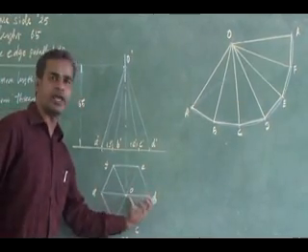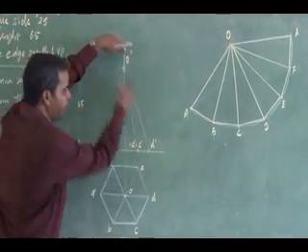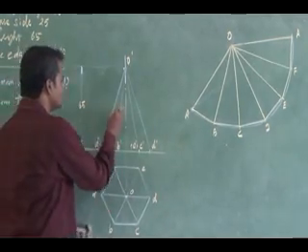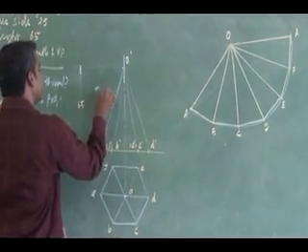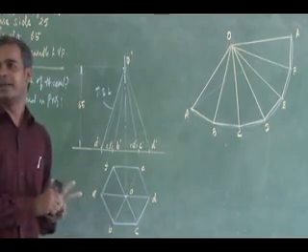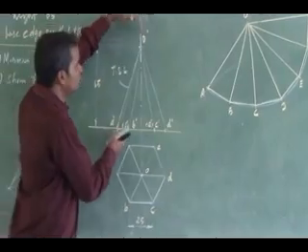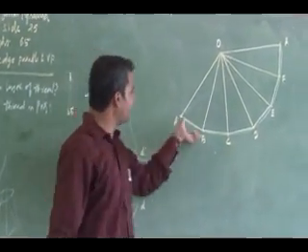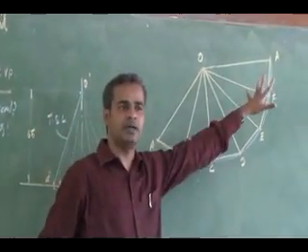So OA and OD in this orientation are parallel to VP. So in the corresponding front view, either OA or OD will give me the true slant length. Directly it will give; I need not rotate. Is it clear? Measuring OA or OD, using that I have drawn everything. Since it is a hexagon of side 25, I have those 25 segments. I have drawn the development.